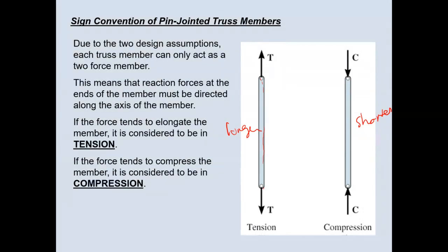So two scenarios are possible for every individual constituent of a truss structure. The first scenario is that the member is in tension. The second scenario is that the member is in compression. Tension makes the part longer. Compression makes the part shorter. In neither way can you have a member changing its radius of curvature.